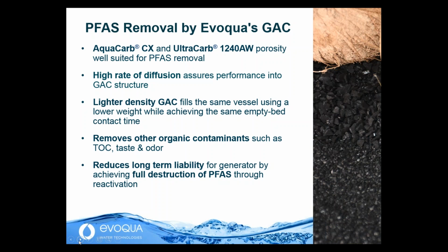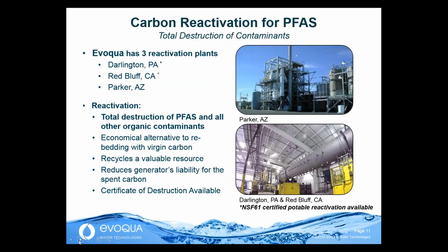As I mentioned before, GAC will also remove other organic contaminants such as TOC and taste and odor. And this is a point that we know is important to a lot of the municipal folks that might be on the phone, but it reduces the long-term liability by fully destroying the PFAS through reactivation.